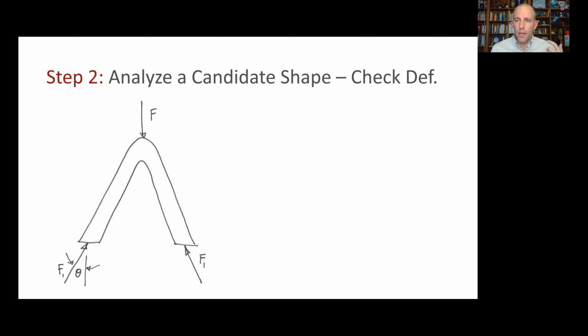And then think about what do we know about how it will definitely move. And in this case, if we push down here with a force, this point should probably go down. So usually you'll see that if you push on something, there's at least a component of the movement in the direction that you pushed. And then try to draw a deformed shape that's consistent with those things.